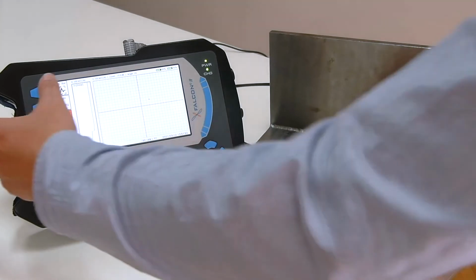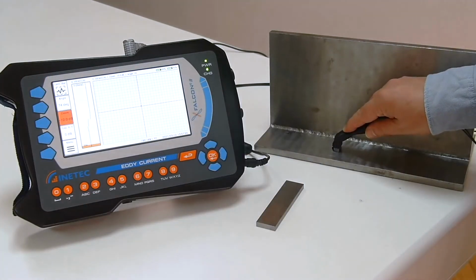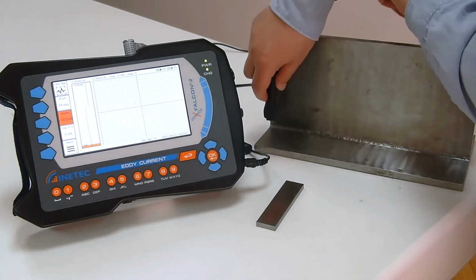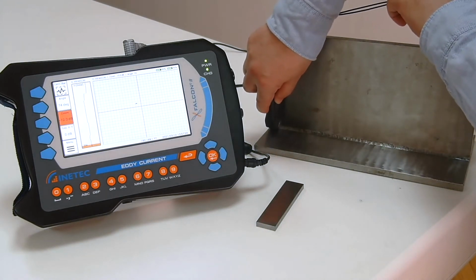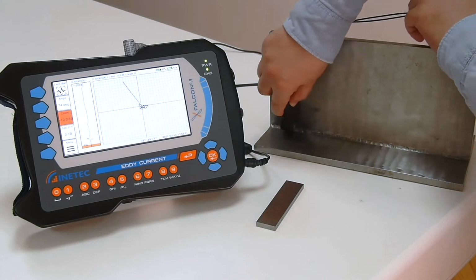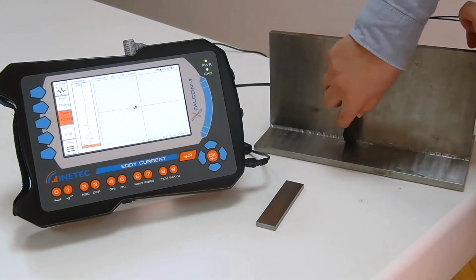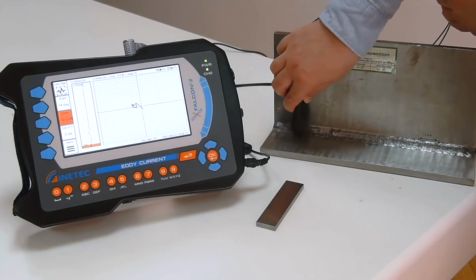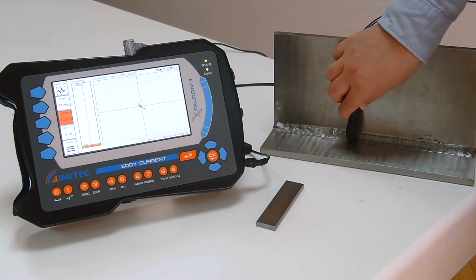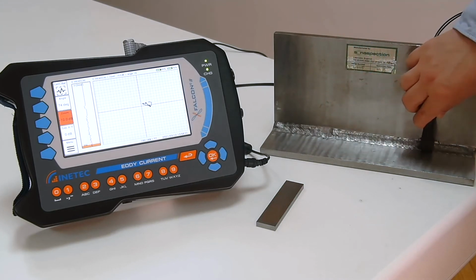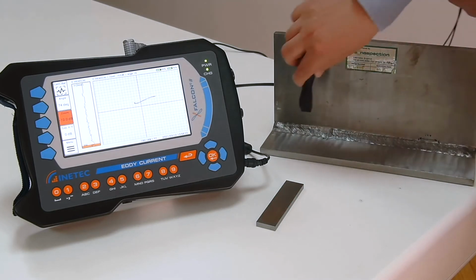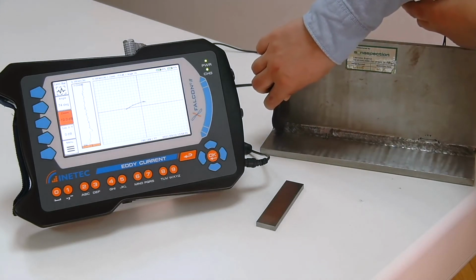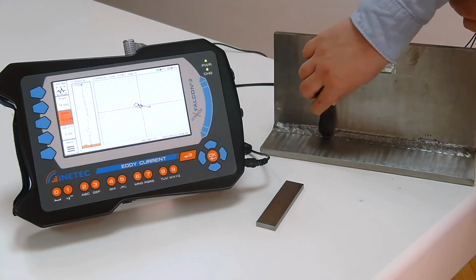Weld inspection using Initec-developed Weld probe shows that reliable detection of cracks in welds on penetrant and magnetics inspection blocks is possible. That allows for a quicker and more reliable method to be used without extensive preparation necessary for other surface inspection methods. A special probe developed in Initec laboratory is designed to minimize the lift-off effect on the uneven weld surface.